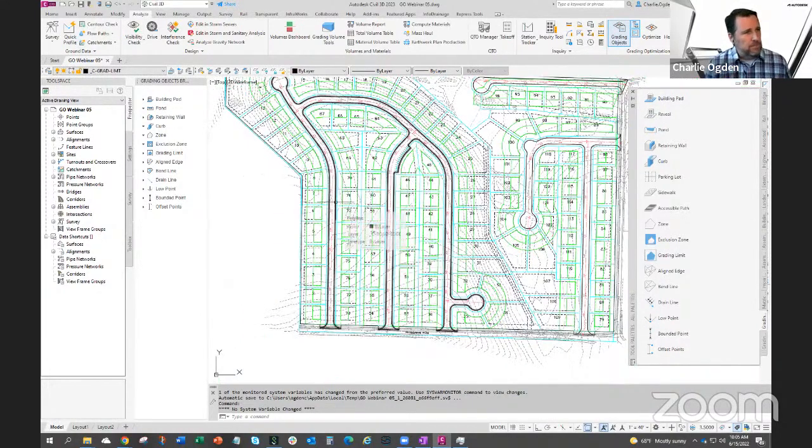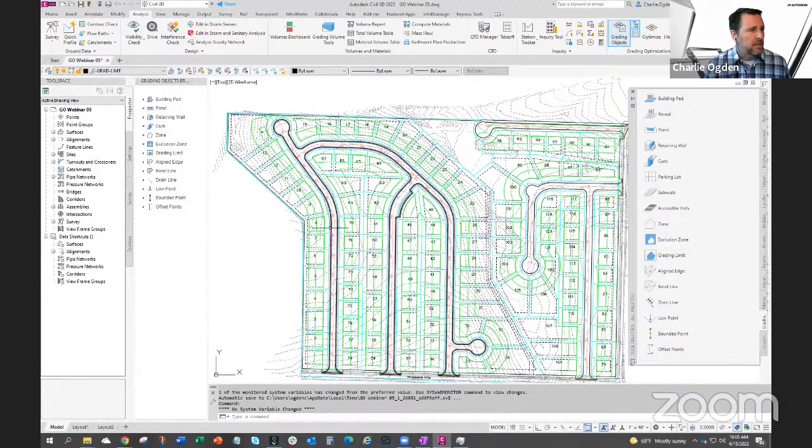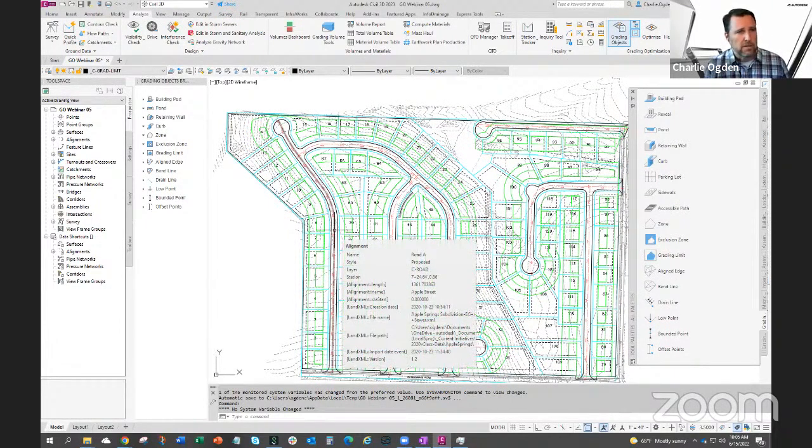So to work around that, what we're going to do is after we balance the whole thing and get an optimized surface with kind of really focused on the roadways at first, and the slopes and requirements kind of in the road area, we're gonna take that optimized surface, go back to Civil 3D, create profiles along there that would then be built into corridors, and then we can take the corridor surfaces, paste it into our optimized surface, bring that back, and we'll show how to not grade within this corridor area, and then work on grading the whole rest of the site.